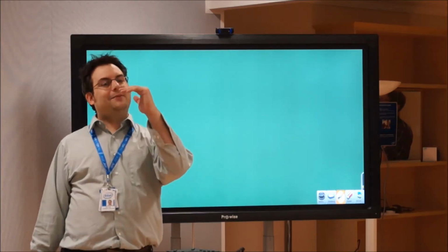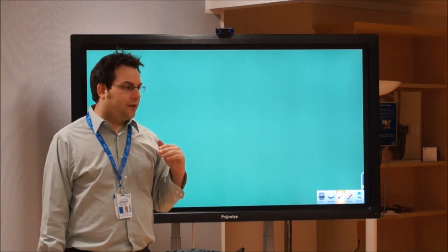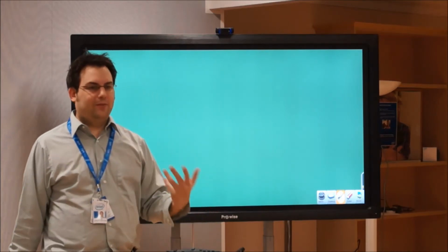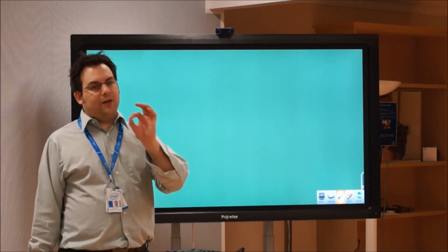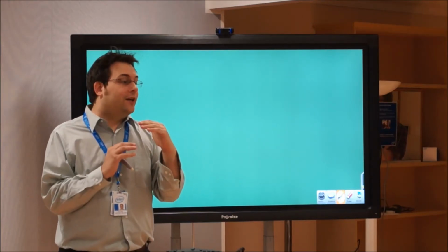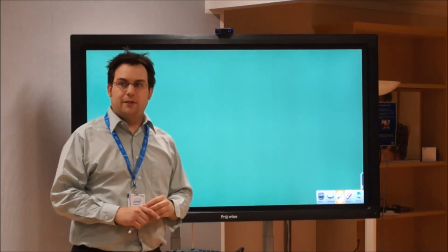Now, most people never really hit the TDP limit on the processor, so probably were never really limited by the amount of power that they were drawing. Okay, so you can leave it at defaults and it probably overclocked just fine. As we went up through the families though, you'll find that the dependence on the amount of power you give the system suddenly affects the length of time you can run at a particular frequency.